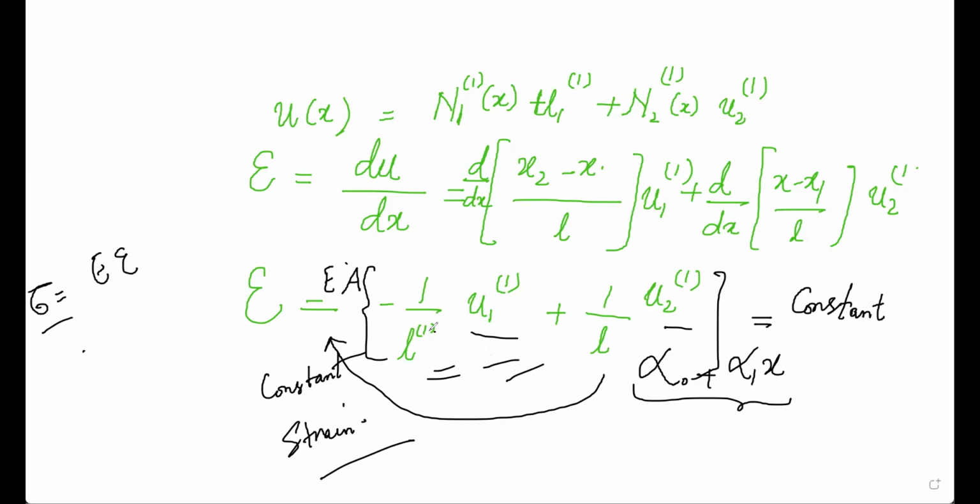But somehow we need to modify our finite element approach towards these types of problems. This is not simply how we should jump into the finite elements. The procedure of finite element is quite different from the procedure we have just started with, though more or less it is the same. First of all, the finite element procedure will start with a few steps. Step number 1 is writing the principle of virtual work, PVW.